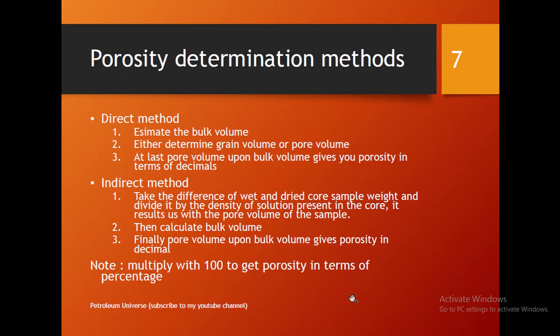By doing this process, you get the pore volume, right? Then by using the data given in the question, you can calculate the bulk volume. Then obviously it is enough for you to calculate porosity if you have pore volume and bulk volume. But you have to note one thing, that whatever calculation you are doing, it will come in terms of decimals. So if you need it in terms of percentage, then you have to multiply your answer by 100 to get porosity in percentage.